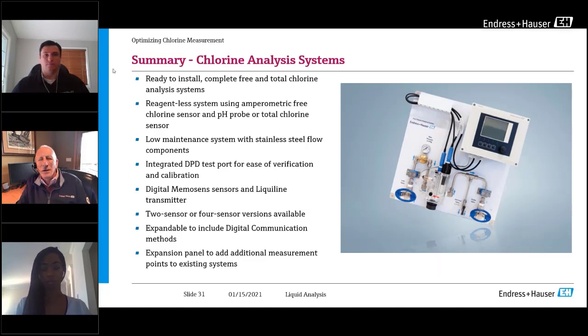That chlorine has combined with ammonia that's in the water or other materials, and it has formed chloramines. Now, as I said before, chloramines are an example of combined chlorine. Now, if supplier 1 has only put enough chlorine in that they've basically just created a whole bunch of combined chlorine in the form of chloramines, that's what supplier 2 appears to be getting.